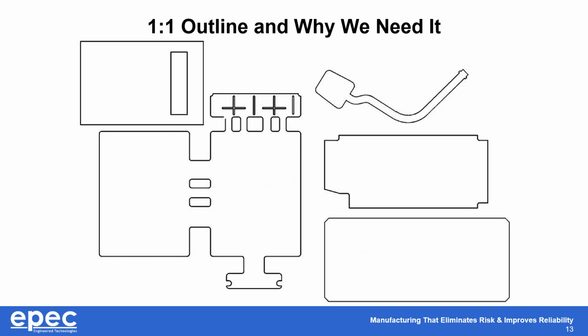And last but not least is your outline. If we receive this in a hand-drawn format or PDF or DXF, any format that depicts what the board looks like. And if you can show us where the approximate place out for a cutout will be, that will help us too. It doesn't have to be perfect, but this is a keep out area. It's a drop through for a cord, or it's just for a component overhang.